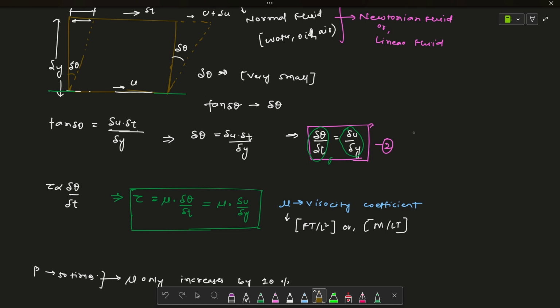That means if we plot the velocity profile for a flow over a plate, like see, this is the plate and some flow is flowing from this direction, due to the no slip condition the shear stress here will be maximum. That means the velocity gradient del u by del y is maximum at the wall.